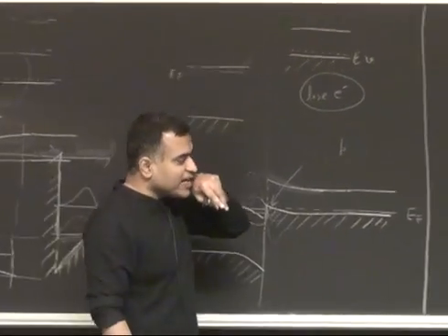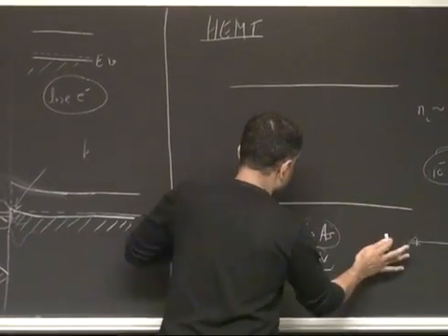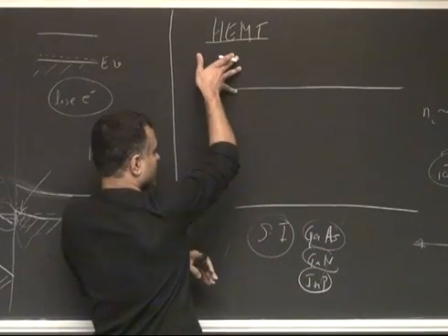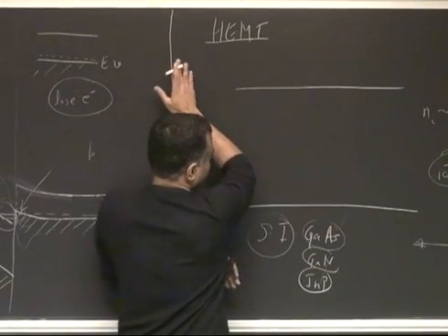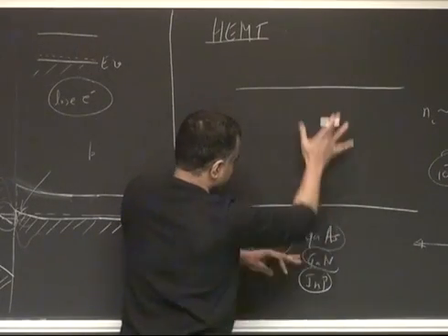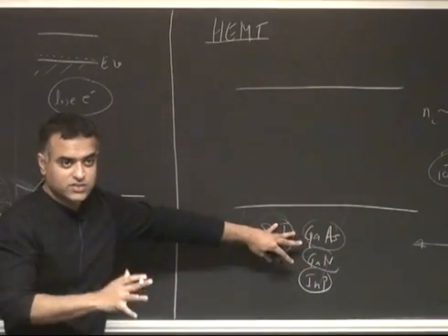So there it's extremely important that this layer be very insulating, because if it's conductive and you're looking at an RF signal, the electromagnetic wave that goes here is going to couple to this conductive region, and there's a huge amount of loss. So it's extremely important that this region is insulating.